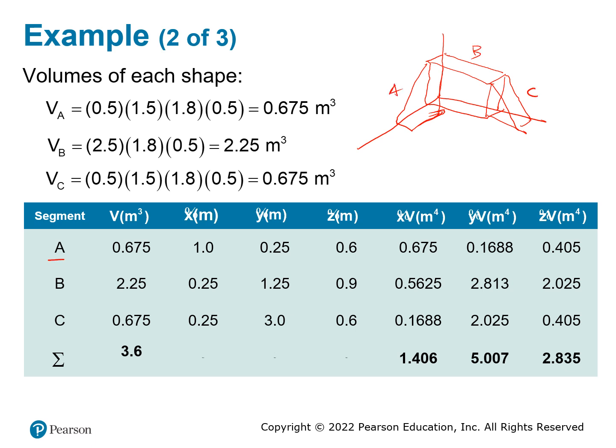So for the A, you find the volume because there is a depth. For the triangle, you just find the triangle area, you multiply with the depth, then you get the volume. So the volume is equal to this. And you have B, which will give the volume. This one should be very simple. Now over here, this is the x tilde, the centroid of each one of the pieces, and you look at each one of the orientations.